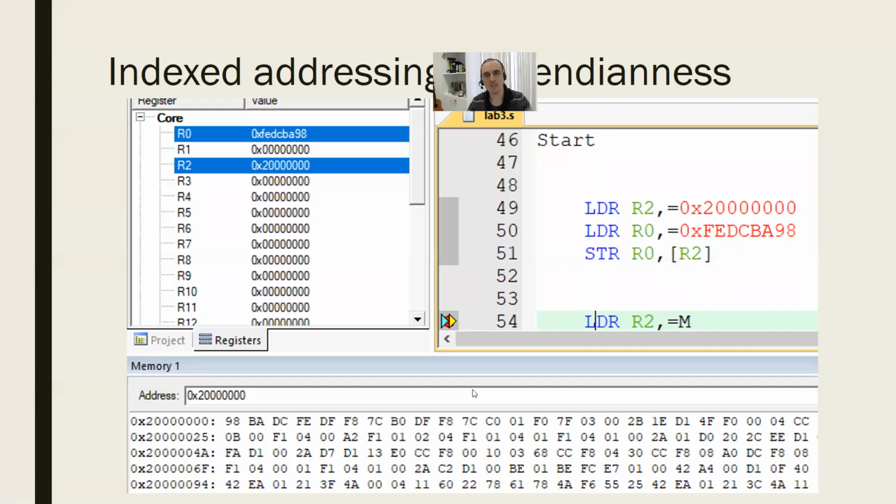So guys, we are going to do this today. You can observe the memory in Keil as well. When you write something in the memory, you can observe those values and see what values you have. For example, I have done some experiments, and this is debug mode. As you can see, I have the yellow triangle, which means I am about to execute this line of code, which I have not yet executed, which means I have executed these lines of code.